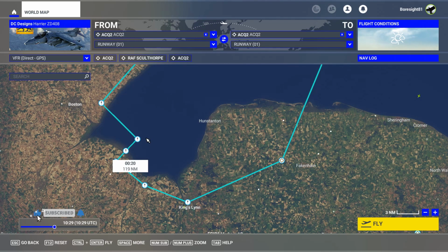you can. There is another popular method, which is CCRP, which is the continually computed release point, and this is slightly different, where the point at the bottom of the plumb line isn't the impact point but the point of release. So what you do is you follow your plumb line to the target, hold your pickle button down, and then you'd get a countdown timer and the bombs would release once it gets to 0, and then again you make your way out.